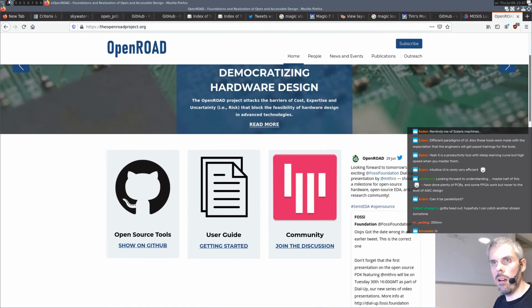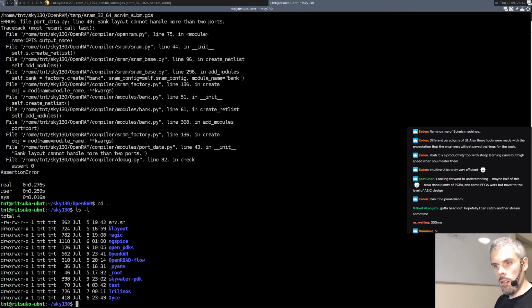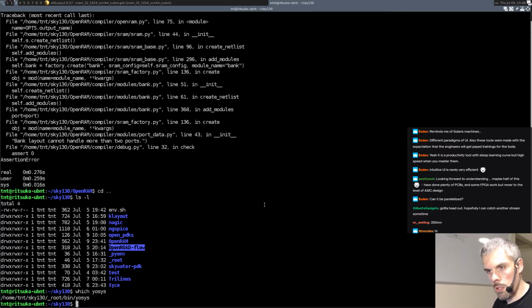Let me see if I can quickly run a design through that. So again, the OpenROAD flow, the official one, isn't published, finalized yet. I just quickly hacked something together so that I could at least run the synthesis part. So here, if I type, I have the special Yosys. I need a synthesis script,